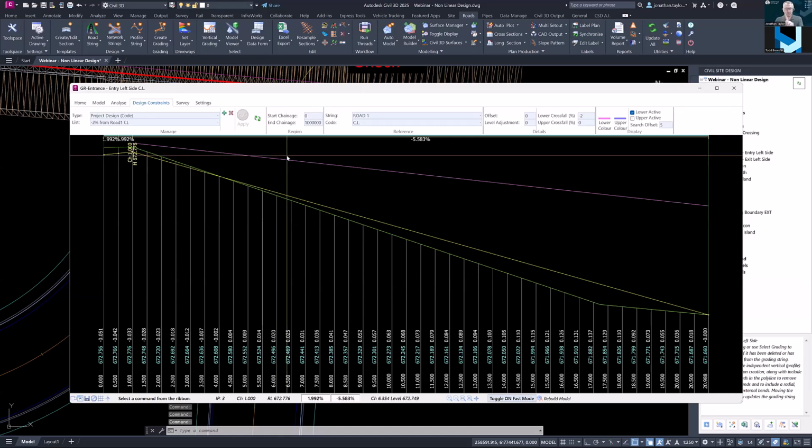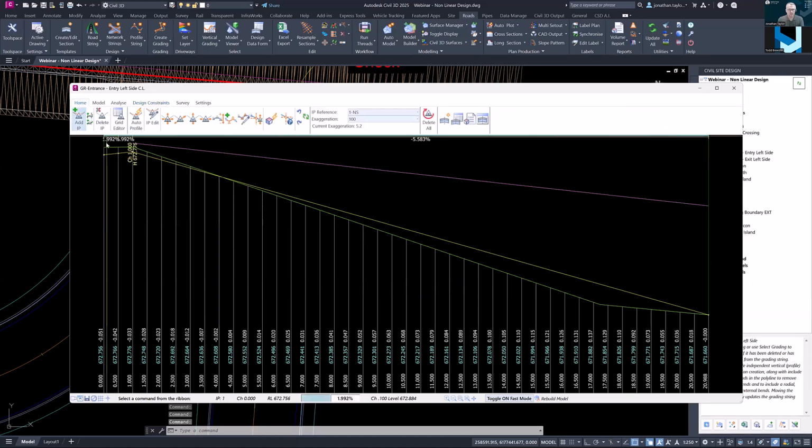So to match onto this constraint, there's two ways you can do it. We can go to the Home tab. You can either pick the constraint. You may not know this, but you can actually snap onto a constraint. You can pick here, and these snap tools snap to whatever reference is in this form. So normally, if you've used this, you've probably gone, well, it always matches to the NS. That's because the NS is listed in here. My constraint is there. Watch what happens when I now use the picker tool.